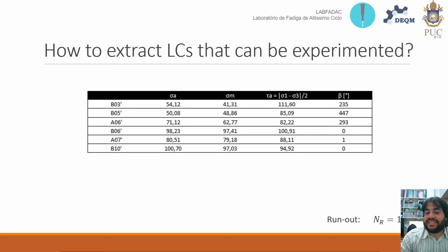Therefore, it was decided to generate an additional couple of loading conditions that could be, within the same methodology, slightly more aggressive to the specimens. The greatest in-phase and the greatest out-of-phase loading conditions were selected, and by considering the amplitudes equal to the maximum stress values, this gives origin to a couple of fully reversed loading conditions with a much greater stress amplitude.